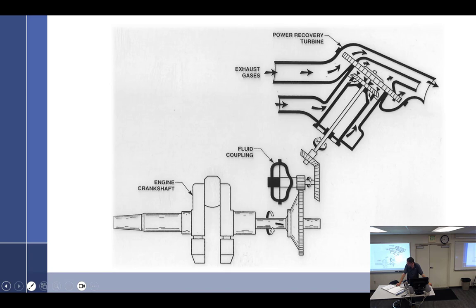If you have a turbocharged system and a pressurized cabin, you're probably also going to have pressurized magnetos. Remember talking about that? Upper deck pressure is vented to the magneto. They changed out the plugs on them so they hold a little more air pressure, but it still has to flow. It's hard on the magnetos because that air is kind of nasty, even though you're using it for the cabin.